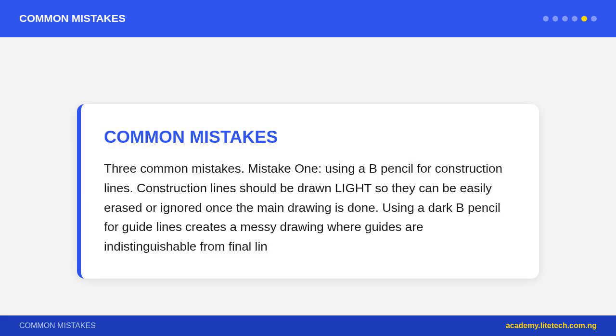Mistake 2. Drawing without fixing the paper to the board. If the paper moves or shifts while drawing, lines will not be parallel or at the correct angle. Always tape or pin the paper to the board before starting.